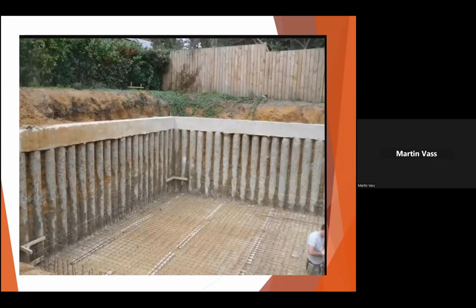What would normally happen, certainly in a place like Durban and certainly Johannesburg, is that if the ground is loose, the ground is not competent, from ground level you'll put what we call soldier piles into the ground, and this will then support the sides of the excavation, and also, very importantly, support the adjacent properties.